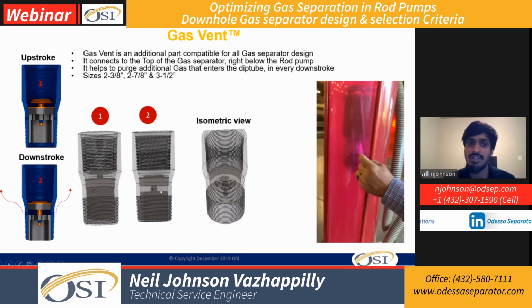So no matter what gas separator we use, we're still going to either have some kind of free gas, whatever we try to separate outside of the gas separator, that goes inside of the dip tube, or hypothetically speaking, we separate 100% of the gas, we're still going to have some solution gas trying to escape inside of the dip tube because of the pressure changes, right? So no matter what separator we use, we're still not going to get 100% pump fillage. But that's exactly why this gas vent system helps in overall increasing the separation efficiency.